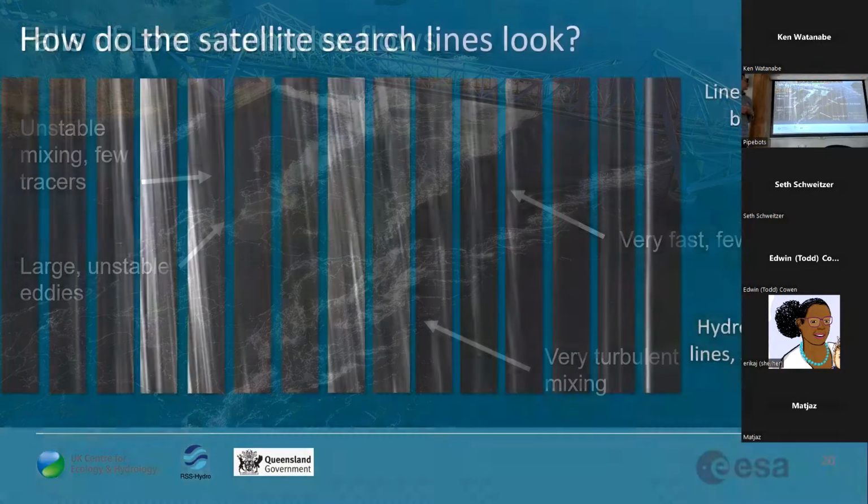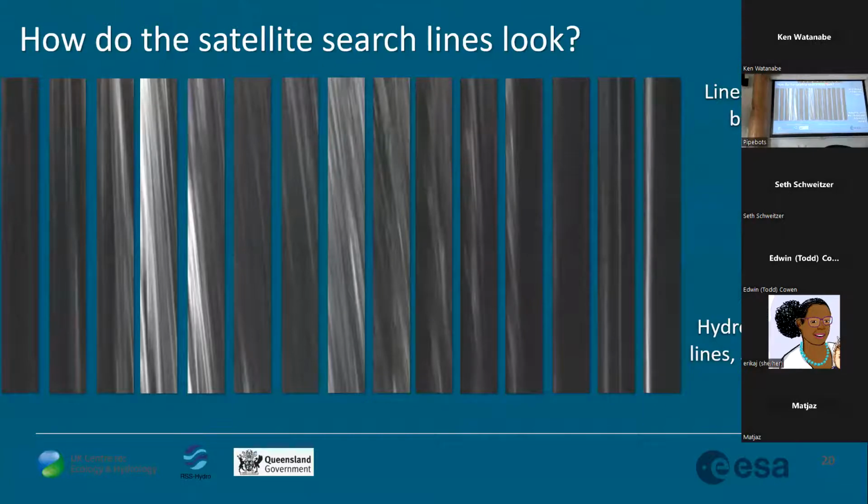Okay, next one. So when we look at some of the search lines, so anyone who's ever used HydroSTIV will be aware that when you do this analysis, we showed you those kind of slopey lines. For reasons I don't fully understand, when I process this, they're not sort of square boxes where it's easy to see the angle. I get more of these sort of sticks. But within them, if you look at these ones here, it's pretty clear the lines running through them. So the analysis is pretty robust. But I think if these things came out slightly more square, or we could reshape them, it would be easier to judge that angle. So I don't fully understand that. But anyway, the point is you can clearly see the velocities that are represented by these lines.